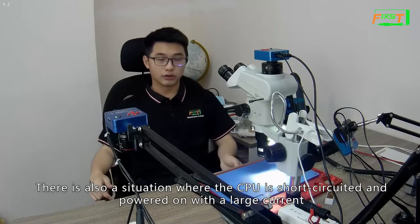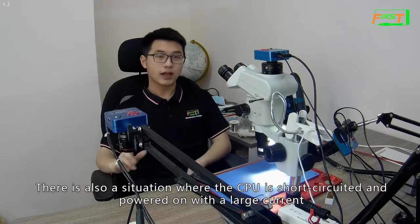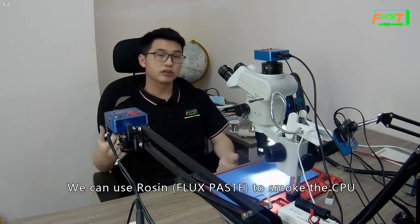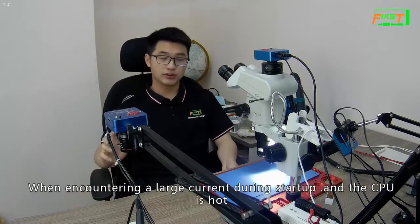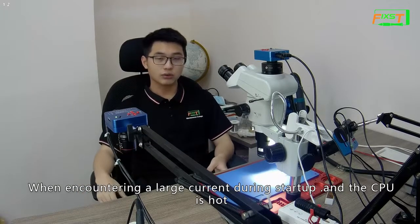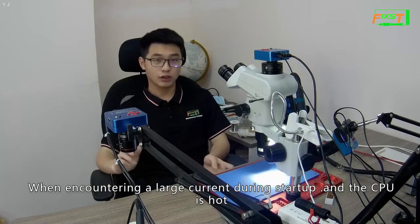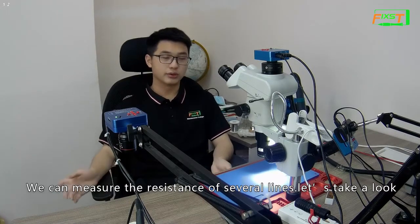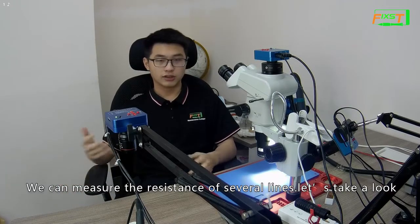There is also a situation where the CPU is short-circuited and powers on with a large current. We can use rosin, also known as flux paste, to smoke the CPU. When encountering a large current during startup and the CPU is hot, we can measure the resistance of several lines. Let's take a look.